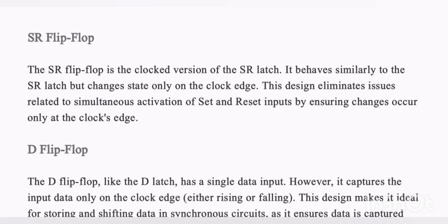SR flip-flop. The SR flip-flop is the clocked version of the SR latch. It behaves similarly to the SR latch, but changes state only on the clock edge. This design eliminates issues related to simultaneous activation of set and reset inputs by ensuring changes occur only at the clock's edge.